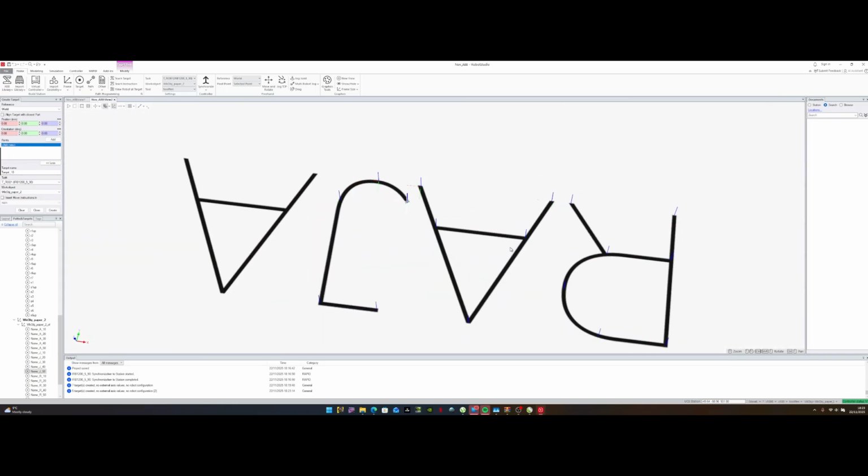So we have a repetition of letters. Now, ideally, for good programming practice, we don't need to recreate those targets anymore. We can just update their x orientation. So this is the x-axis. We can just update their x-axis orientation programmatically. But I'm lazy. I just want to make this thing straightforward. So we're just going to create another set of targets again. So we're going to go back here, create work, make sure the reference is work object, click add, and then we're just going to click on those targets again for the letter A.